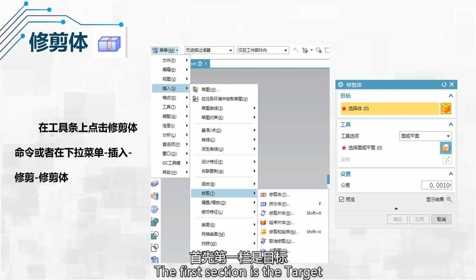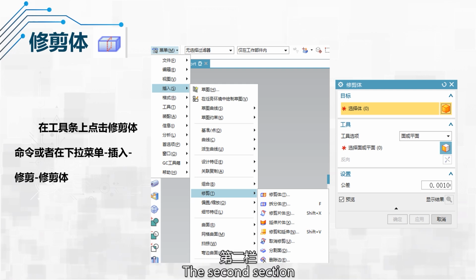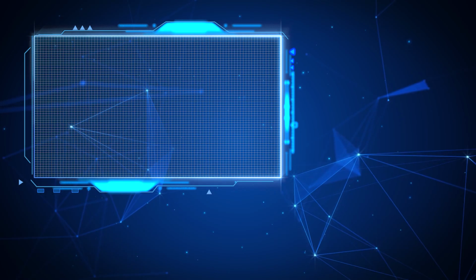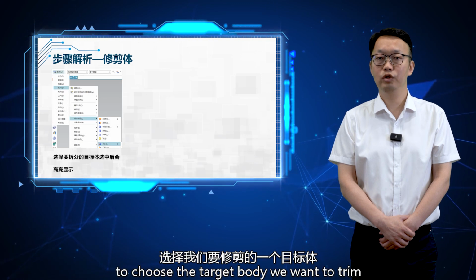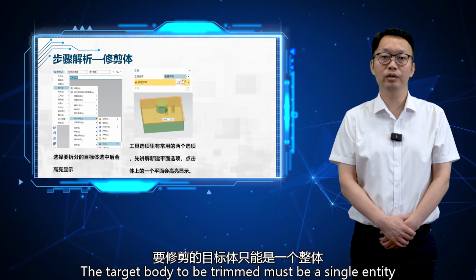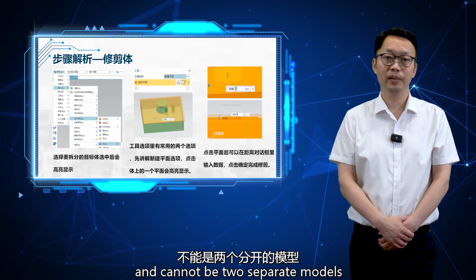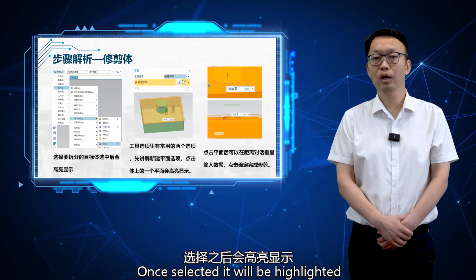The first section is the target, where we select the target body we want to trim. The second section, Tool, is where we choose the plane for trimming and splitting. First, click Select Body to choose the target body we want to trim. The target body must be a single entity and cannot be two separate models. Once selected, it will be highlighted.